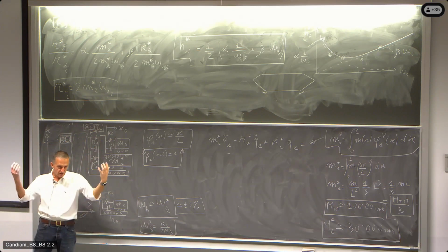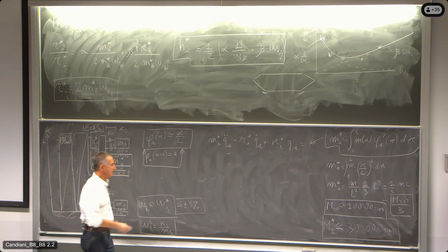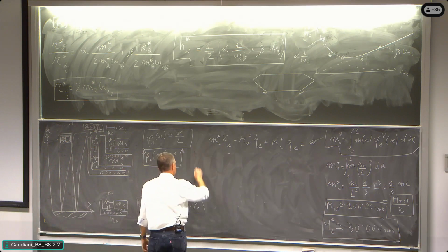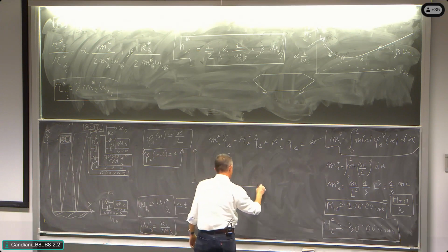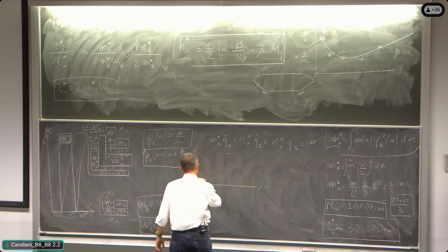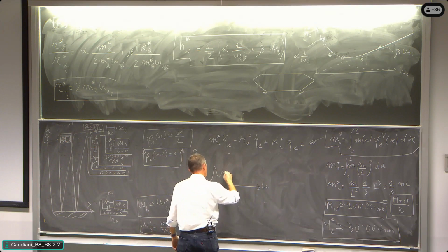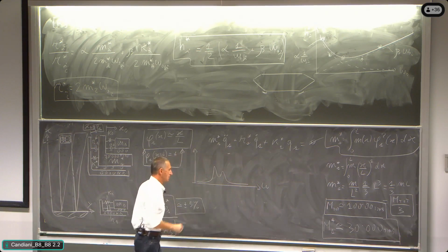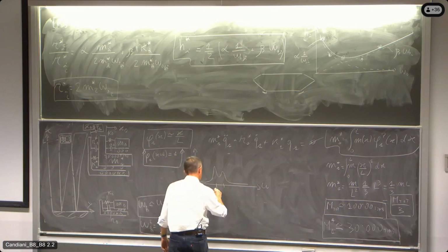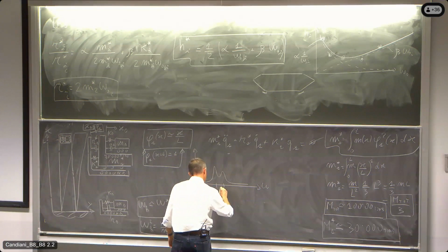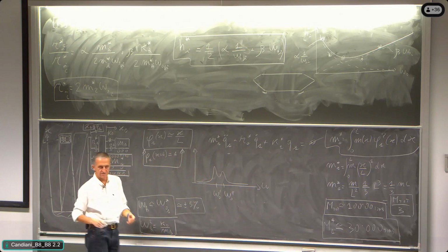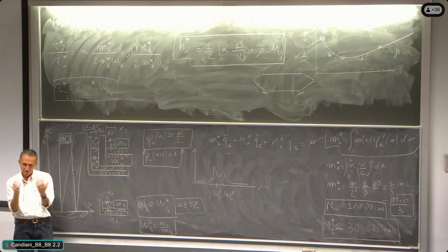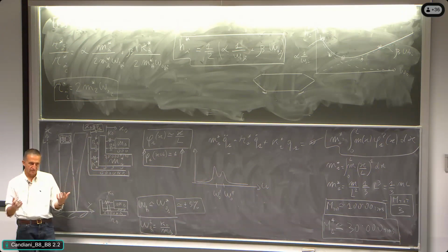I write two equations, and so it is a 2-degree of freedom system, and so the behavior of this object will be a behavior like that, where I recognize two peaks. I have two natural frequencies, all right? I have two natural frequencies because it is a 2-degree of freedom system.